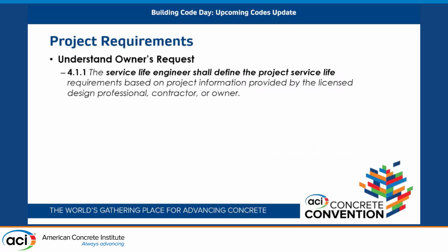One of the most important, or perhaps the most important, aspects of this is we need to have a clear understanding of what we mean when we say service life. For an owner, it can be, okay, I don't want to have to do anything. For another owner, it can mean, well, I'm going to have maintenance and monitoring crews every 5 to 10 years until we achieve the required service life. And that is a big difference.